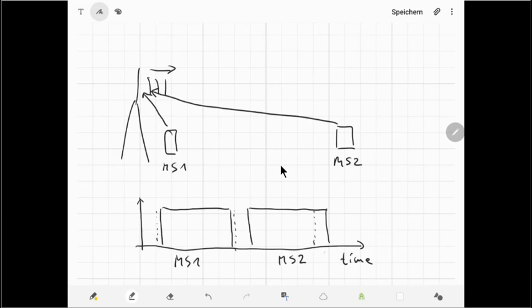And if you would now start again with the reception from mobile station 1, then you would get a collision here in this area where the mobile station 2 is not finished yet, but the mobile station 1 already starts with the next package. In reality, this would not be mobile station 1, but it might be another station which has this third time slot assigned, and then the collision would happen here again with mobile station 2.